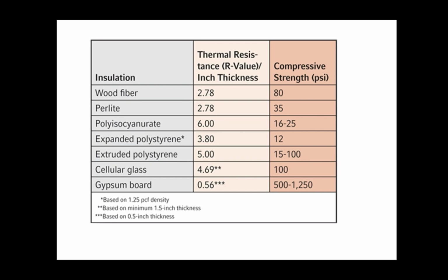Every material has what we call a thermal resistance, and that basically links to your insulation value, so you know how good it is. That R value gives you an indication as to how good an insulator it really is. Right, and so you see there some of the typical insulators, some of the typical materials, how good they are at insulating and what the thickness would be for some of those insulations, as well as compressive strength, because sometimes it's not only used as an insulation, but it's added as an additional support.